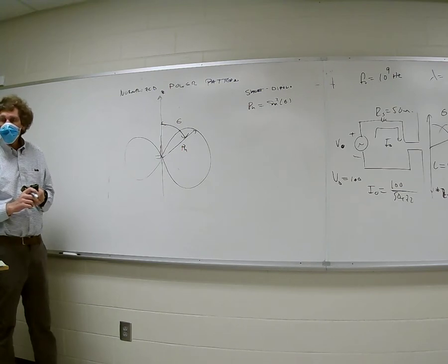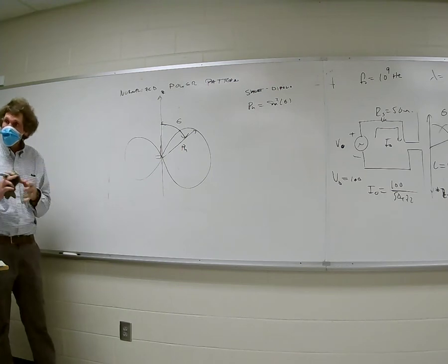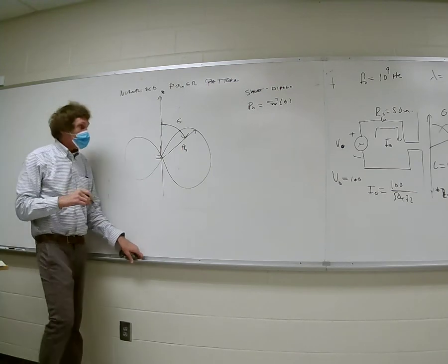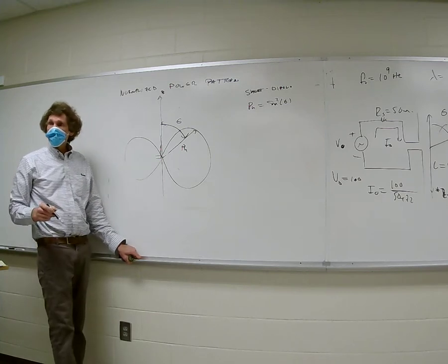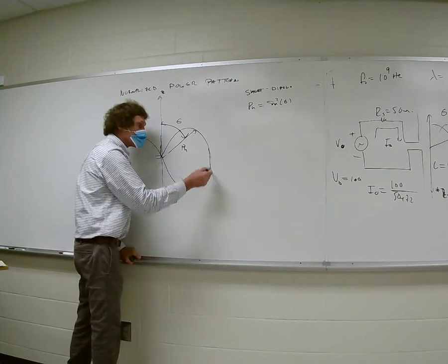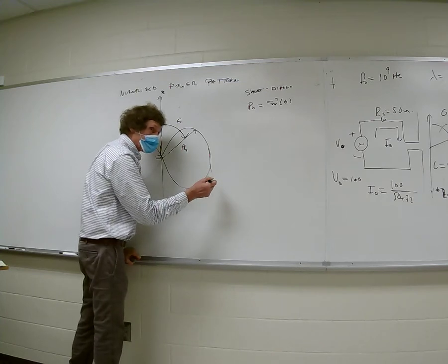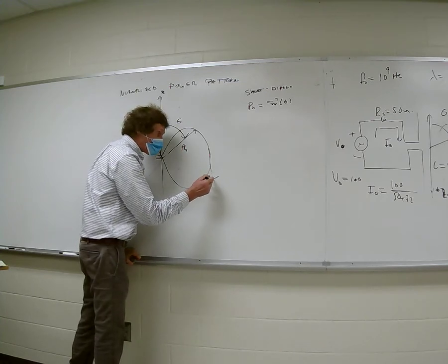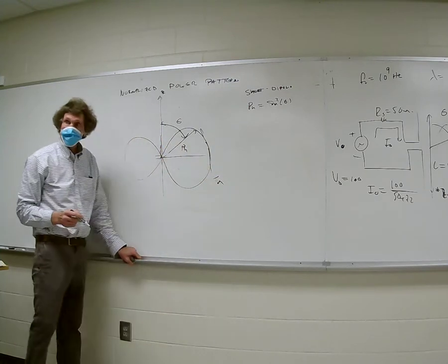They would say it would be the normalized gain pattern as well. You don't have to worry about any of this really, other than you all see how that was the normalized power pattern, right? Now if you wanted to know what the gain was, then you come out here, instead of having 1 out here, you just have this times D max, all right? And for a short dipole, it would be 1.5, and that would occur right out here at 90 degrees. Are you with me? But it's a dumbbell.